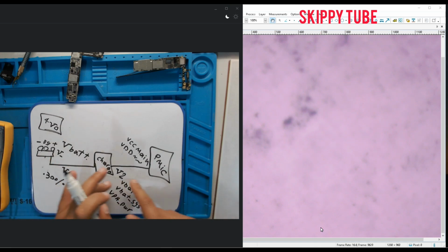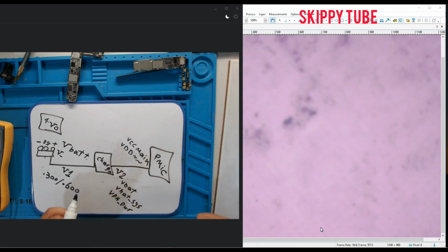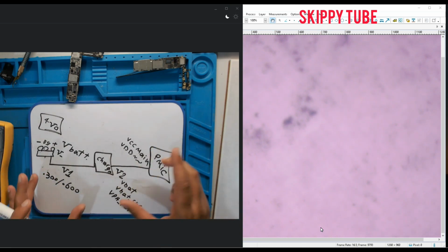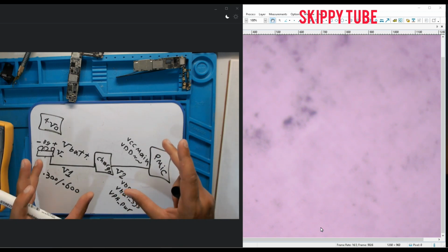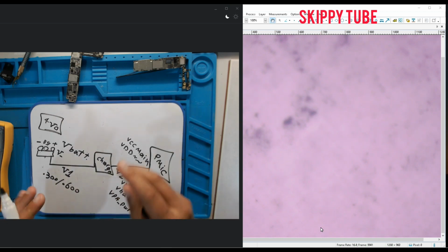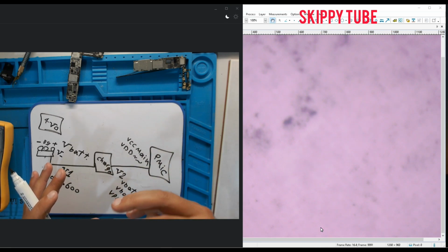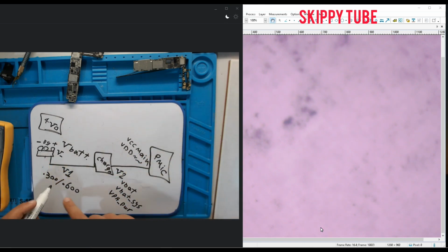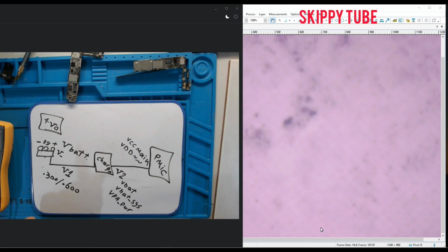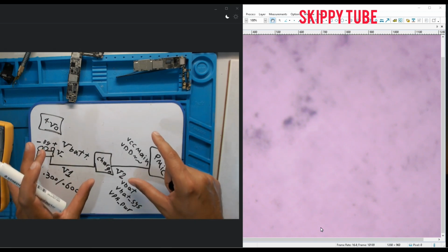For simplicity, I explained these two-side voltages: I said voltage 1, voltage 2. Voltage 2 is between the charge IC and the PMIC. Okay, these two sides have the same diode value. That means between 0.300 and 0.600, there may be a 10 percent fault tolerance, and this side is the same. It's like that, but you need to pay attention to this diode value.